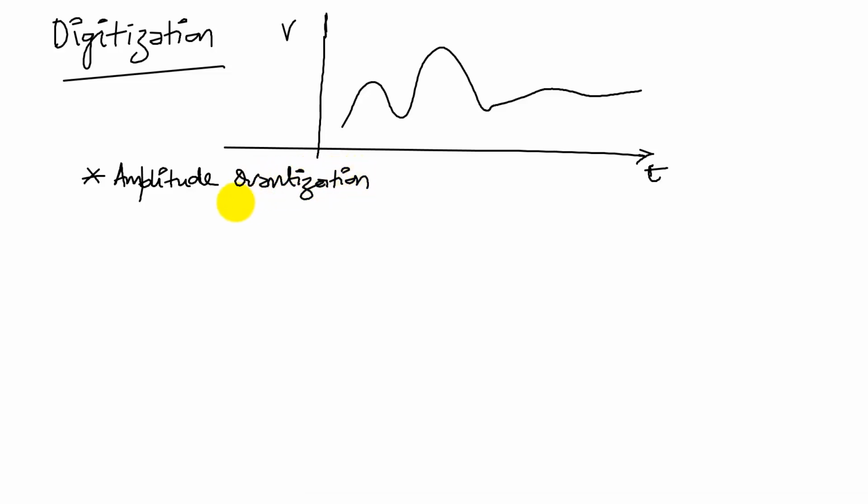So by quantization we mean discretizing the signal. So we have continuous, the opposite of continuous, that as far as the computer is concerned is discrete. So when we store our information in the computer, we store them as digital values. So our amplitude quantization is talking about separating our amplitude into levels. So we'll call these levels.